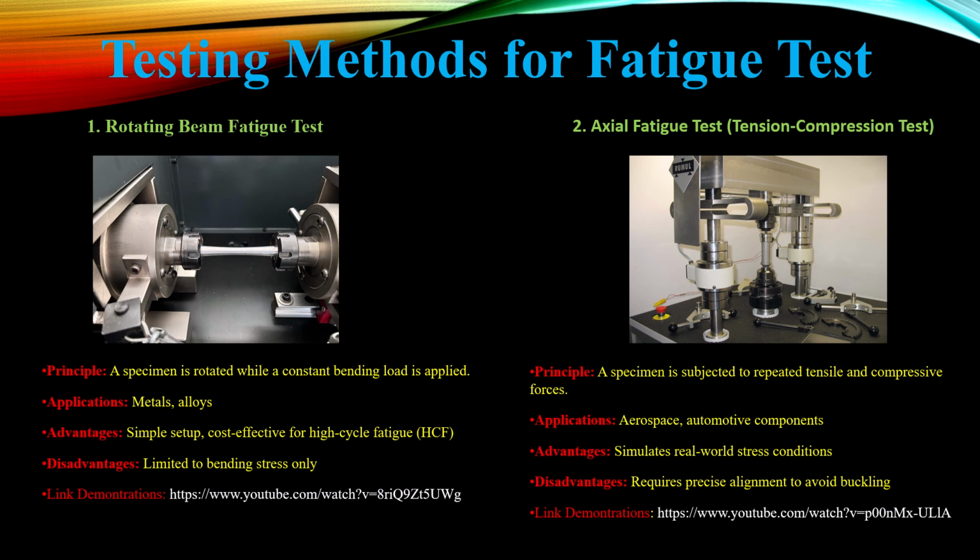in real-world applications. The second point explains the axial fatigue test, also known as the tension-compression test. In this method, a specimen undergoes repeated cycles of tensile and compressive force. This test is particularly valuable for evaluating components in the aerospace and automotive industry, where materials experience similar real-world loading conditions.